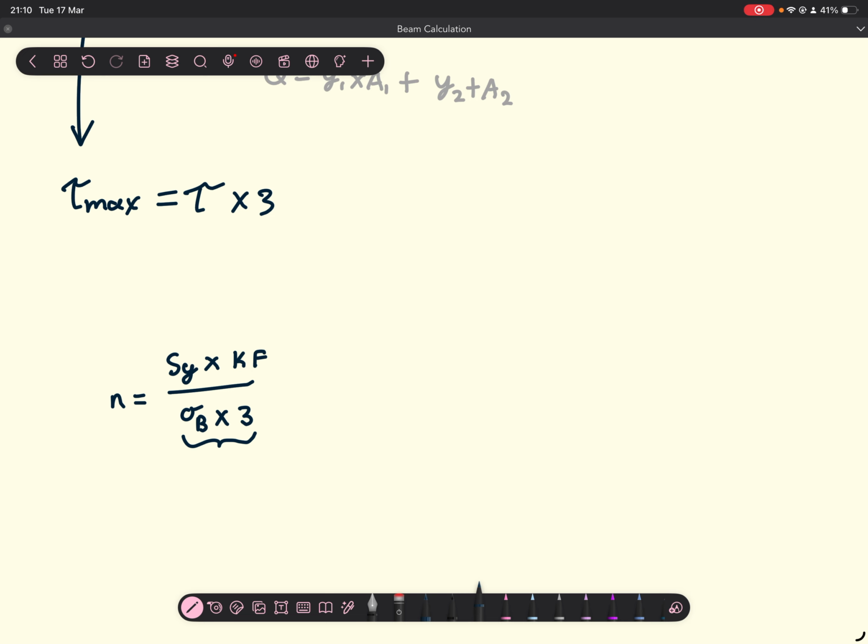Again, we're considering the case where everything has gone wrong and our stress is actually 3 times, so that safety factor doesn't matter anymore, right? Because we're already on the limit of what we've designed for. And then our yield strength, so our material is 10% weaker than it should be. So let's say we've reached the worst case scenario where our yield strength is 10% less than it should be and our stresses are 3 times as high. So what would then be our safety factor? Are we still safe to operate, or is this thing just going to fail?